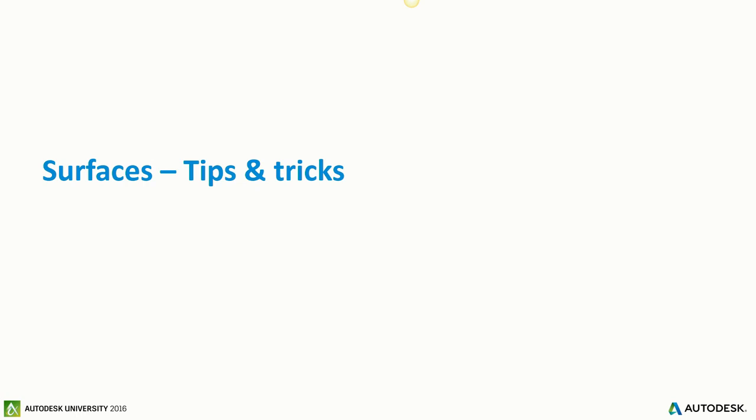How many of you have made a surface and seen in the event viewer that you got 2 break lines that are crossing? Right? How do you resolve it? Well, there are a multitude of ways to resolve. But what I'm going to show you is one little trick. If you have been through the handout that I gave you, you know it. If you're not using it, you should. There is one routine that I'm going to show you that does that.